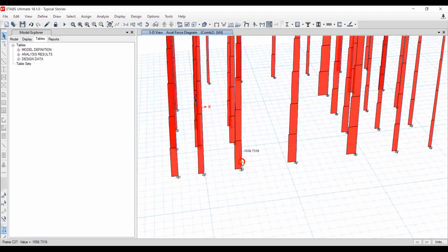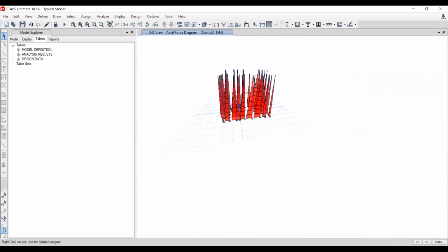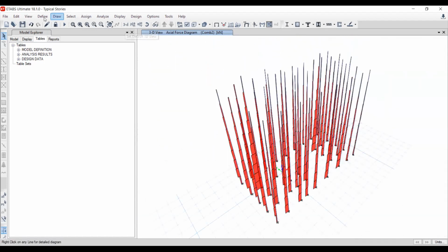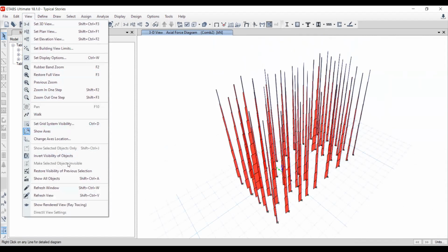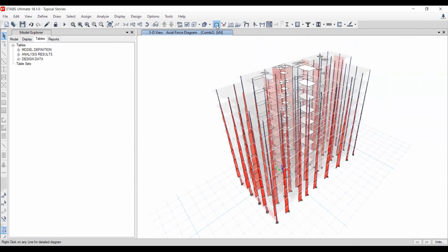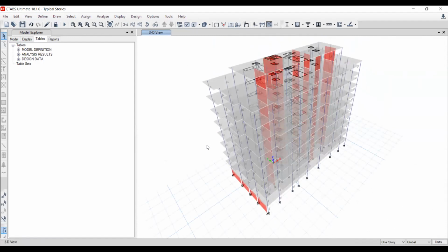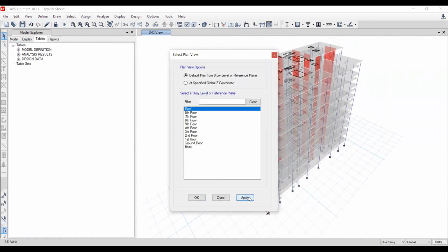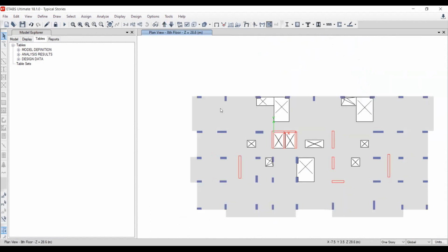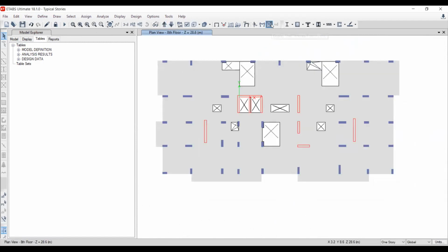This is axial forces. So if you select the object on show object percentages, now we know the drift and the sway are okay. We define the load combination. Now we need to know the deflection of the slab. In ETABS, deflection of the slab is difficult to read.